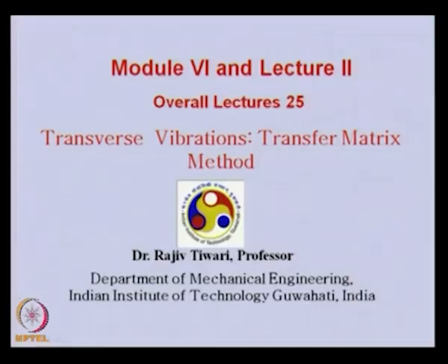Today we will study transverse vibration using the transfer matrix method. This particular method we studied earlier for the torsional vibration case. We have seen the advantage of this method, that it can be applied to a multi-rotor system. Once we develop the point matrix and field matrix for the disc and the shaft, we can use this for larger systems also.